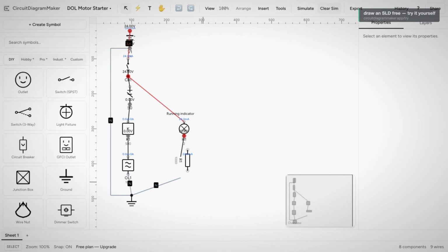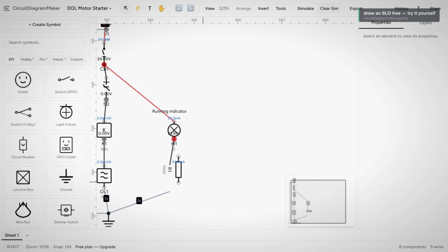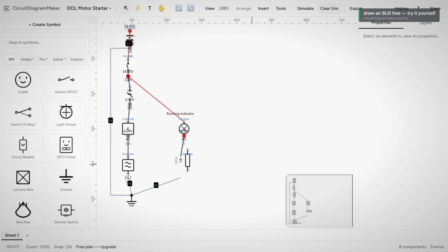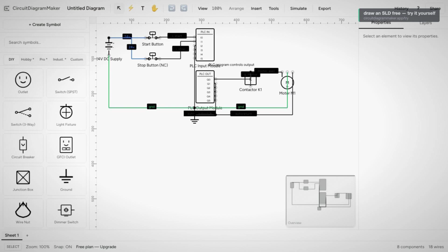This is your sanity check. If a feeder is wired wrong, the numbers say so before you ever touch a real bus. A 0 where you expected volts is the fastest fault report there is. No meter, no smoke, no guessing. Transient and AC sweep live in the same dialogue when you need waveforms over time. Now, be honest about what this is. It is a real circuit simulation, not a full power systems short circuit study. But for checking that your single line is connected the way you think it is, watching the numbers land is worth more than any static picture.